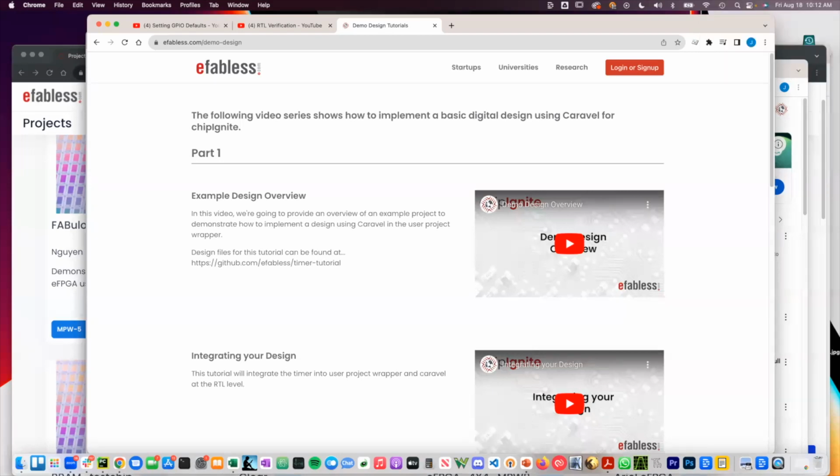Yes, there is, and the default constraints are actually in, I believe, I'm going to check this afterwards, Samarth, but the default constraints are already in, pin by pin for each of the pins on the logic analyzer interface, to do that synthesis correctly and be able to work across the interface. So the SDC and the timing constraints should both be there by default for you to use, and the Wishbone bus interface as well. I'm going to confirm that offline afterwards.